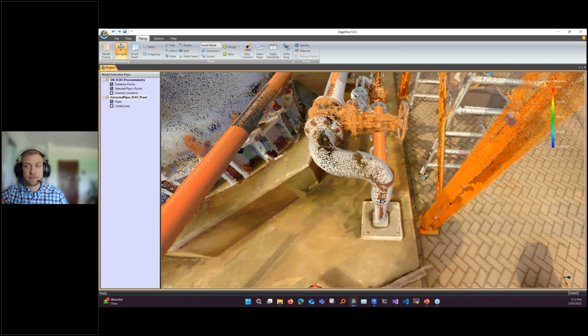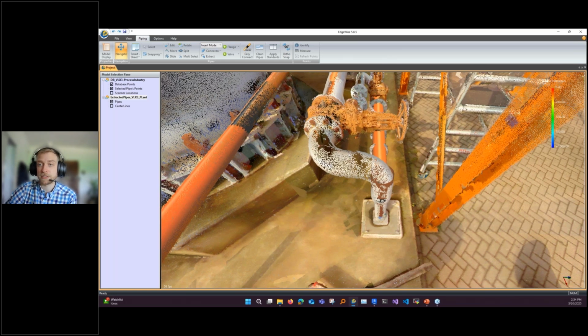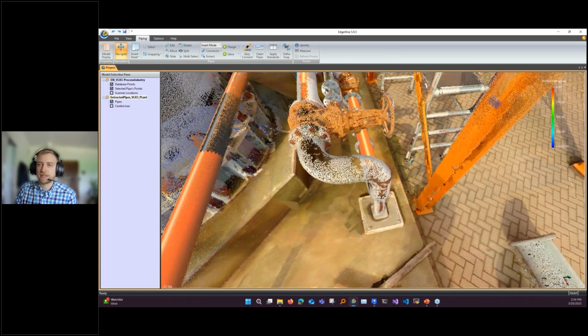And then valves go on pipes. We kind of need a valve object, a pipe object everywhere between all the different components, and so that can be tricky when there is no pipe between two things in the real world. In this case, this is actually looking at it as two elbows welded directly together. Super common. That is a very normal thing in the field.